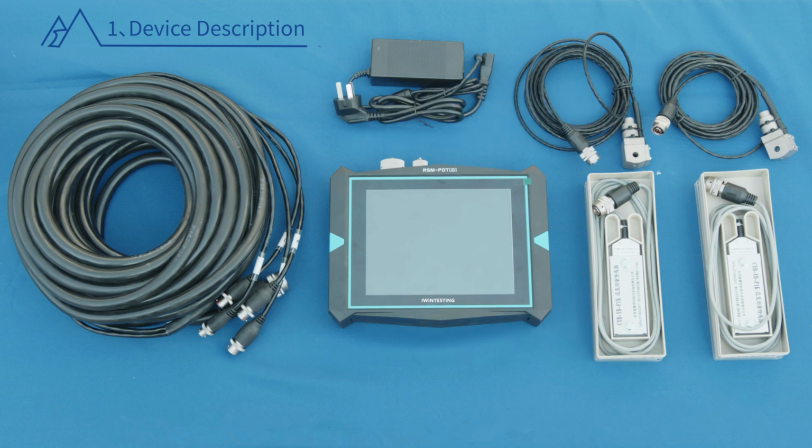When only the structural integrity of the pile is tested, the weight of the hammer should be reduced, the drop distance should be reduced, and the thickness of the hammer pad should be reduced. But it should be ensured that the obvious reflection signal from the bottom of the pile can be tested.